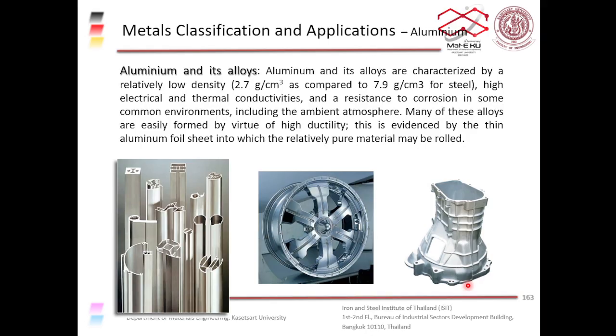Remember, you have to use quite thick cable, and the weight of that cable can be quite high. So if you're using a heavier and denser material like copper, you would have high cable weights, so your pylons have to be closer together to distribute the weight better.